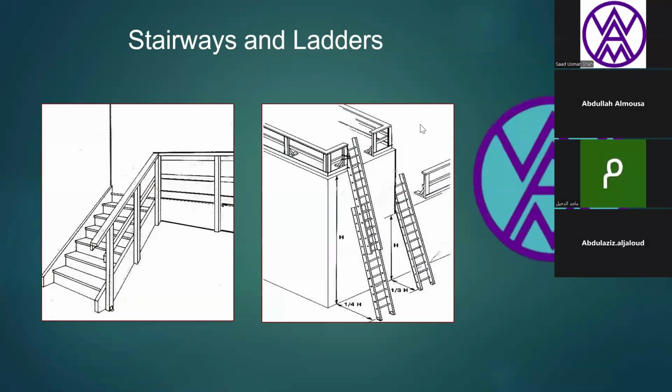Today's lecture is about the stairs, the hazard related to the stairs and the ladders. We will discuss the OSHA standards which apply to your stairs if you are working in industry. You should know what should be the standard according to OSHA. So, one by one, I will tell you about the standards that are implemented. The length of the step and the total area of the step should be a minimum of 10 inches.